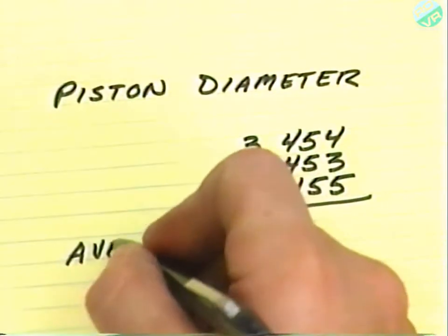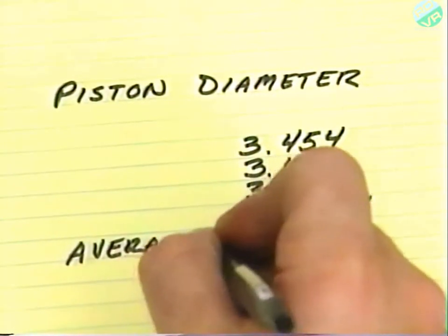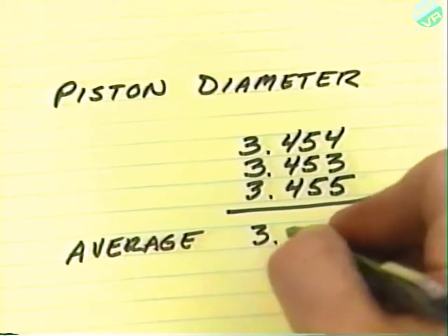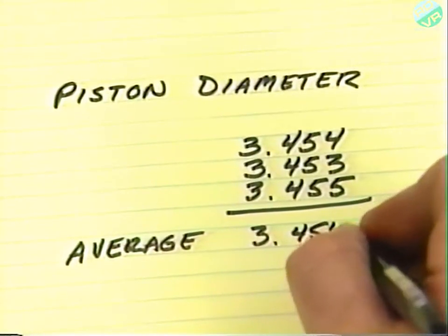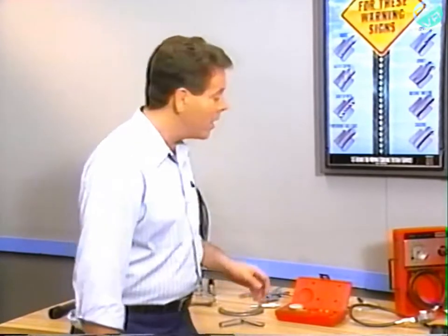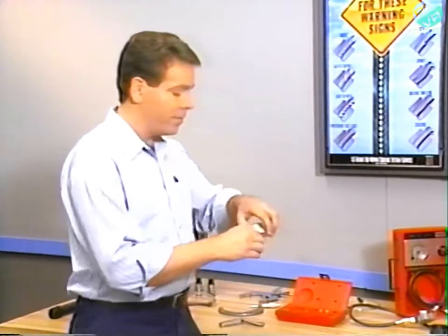Once you have the reading, record it immediately. In fact, the best technique is to take 3 readings and then use the average. Micrometers have hundreds of uses in engine service, so it's vital that you know how to use one. Another essential measuring tool is a dial indicator.